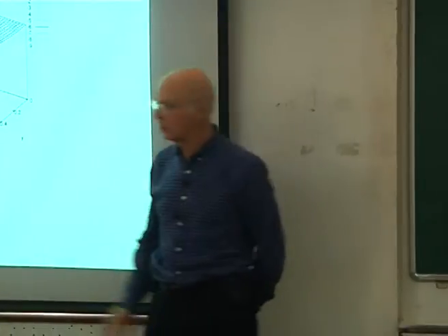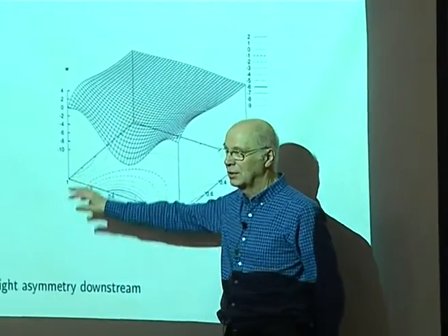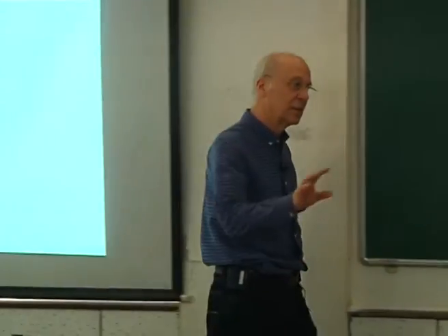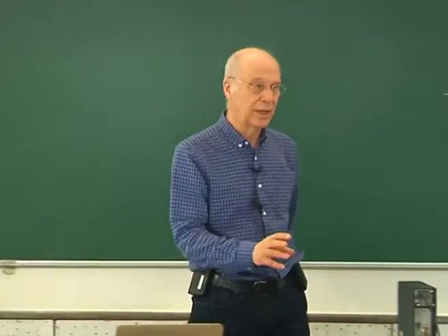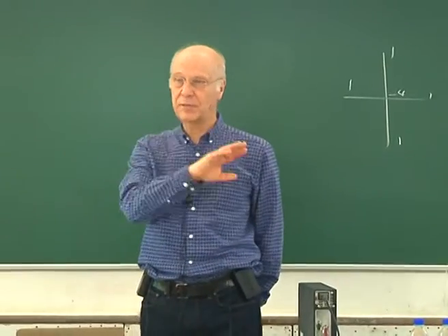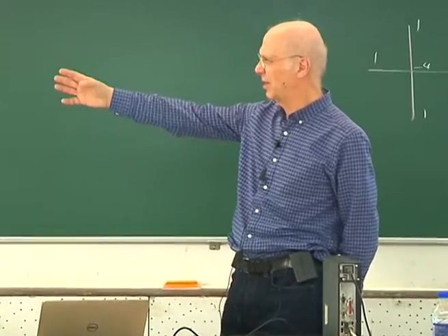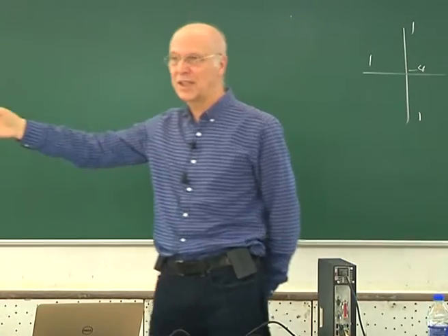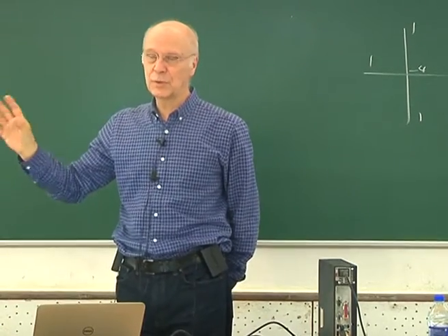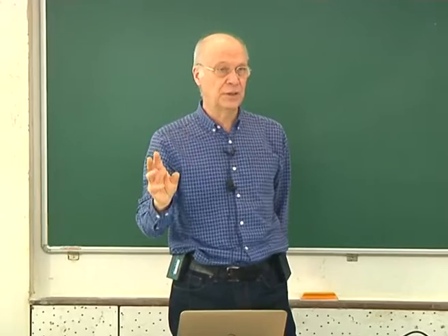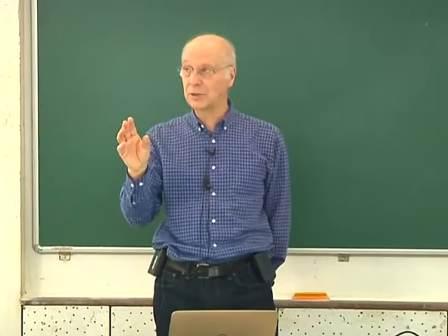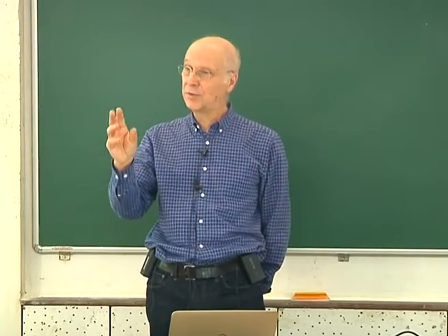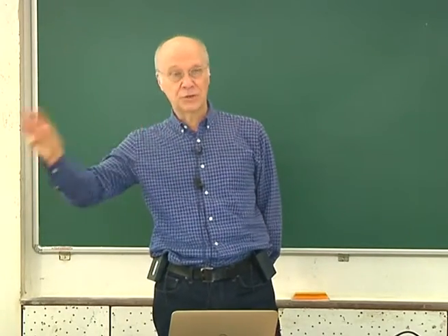That is, advection is moving it. So at Reynolds number 10, there is a slight asymmetry. Reynolds number 1, it would be perfectly symmetric. It's nearly perfectly symmetric here. There's just, in the vorticity, you can see a small asymmetry due to advection. And if we go up to Reynolds number 100, you'll see much more of a difference between upstream and downstream.